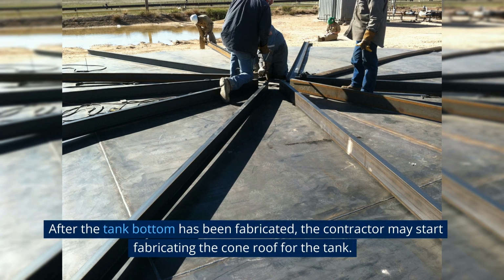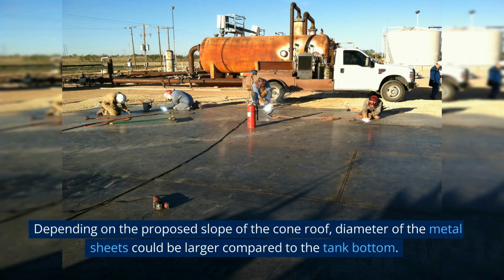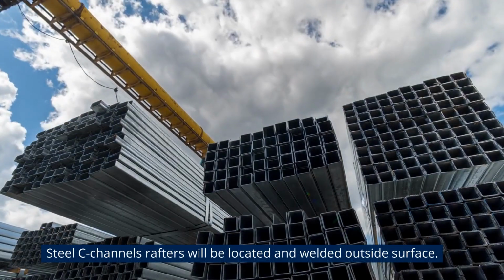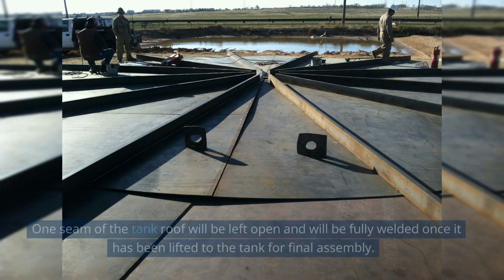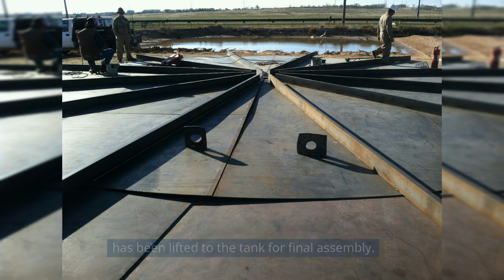After the tank bottom has been fabricated, the contractor may start fabricating the cone roof for the tank. Depending on the proposed slope of the cone roof, the diameter of the metal sheets could be larger compared to the tank bottom. Steel C-channel rafters will be located and welded on the outside surface. One seam of the tank roof will be left open and will be fully welded once it has been lifted to the tank for final assembly.